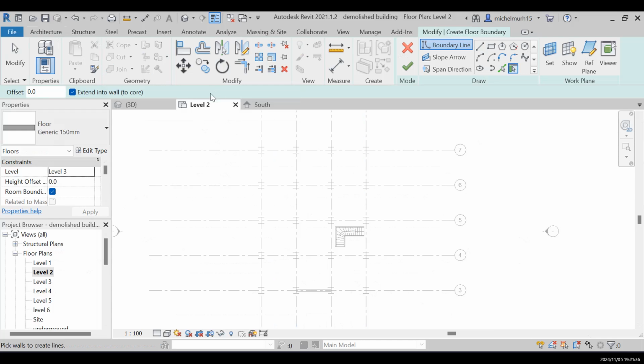As you can see, immediately if I press level 2, the constraint level of the balcony should be above the second level, so the constraint level becomes level 3, but I can change it to level 4. But if I put it at level 2, the computer will ask me to change the level. So if you wanna create a balcony on the second level, you have to set it on the first level.